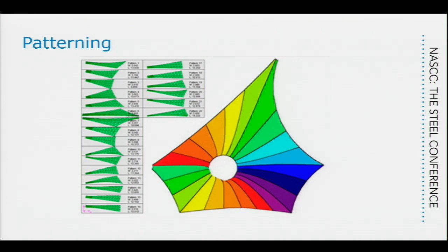The best I can say it is imagine a cloth that is weaved, and then you get two layers of plastic that get bonded to it. So it behaves orthotropically, so it behaves the same if I pull in the orthogonal directions of the weave, but if I pull diagonally on that weave, it behaves differently.